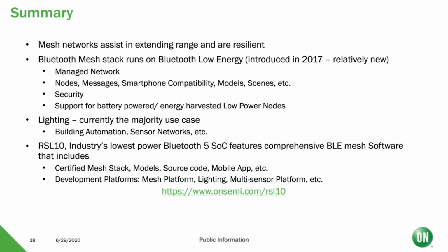It does have very detailed options and features that allow different kinds of nodes, things like friendship, proxy nodes, relay nodes, and low power nodes to all be part of this mesh network. Message formats and everything is very detailed, listing what type of messages are supported, what type of models are supported, and compatibility with smartphones. They're all part of the Bluetooth mesh network stack and protocol.